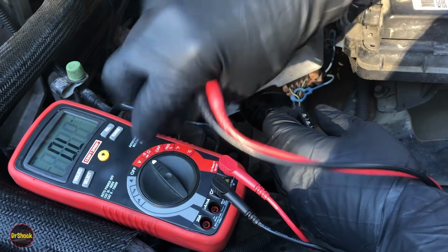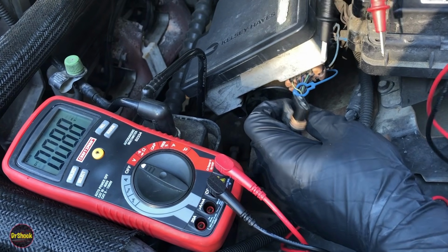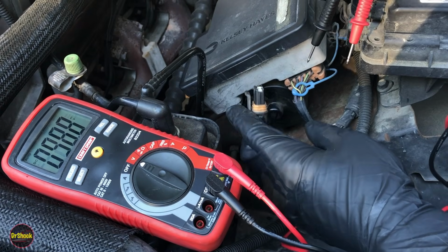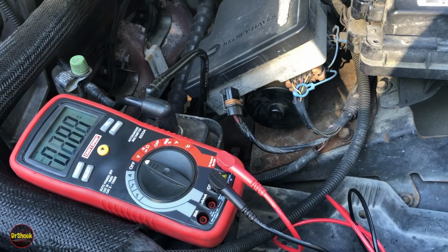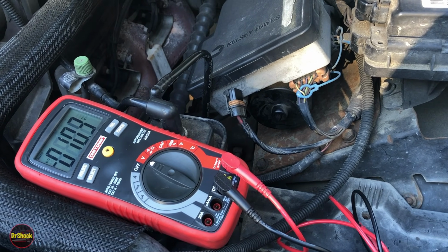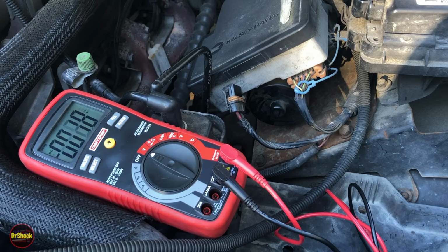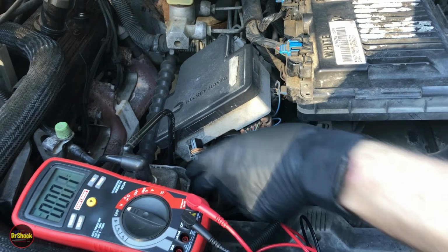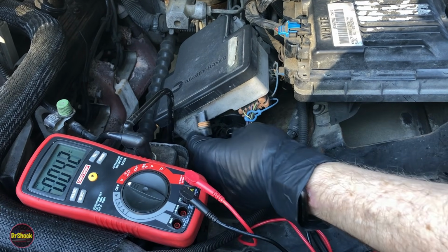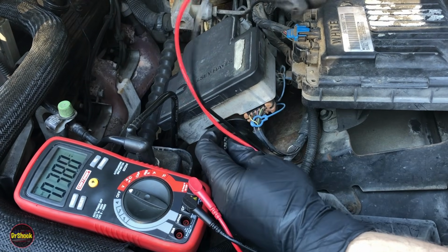All right, so I'm going to turn it to volts, and we're going to do that voltage test that I showed in the service manual. Now, this test requires us to turn the key on, so I'm going to go inside the truck and turn the key on. Now, when we do this, we're going to generate some new codes. The reason is that when we turn the key on, we're either powering up the VCM on these gas trucks or the PCM in a diesel truck, and the EBCM is not connected, so the computer is going to flag that with a bunch of codes. So just be ready for that. You'll have to clear those out.